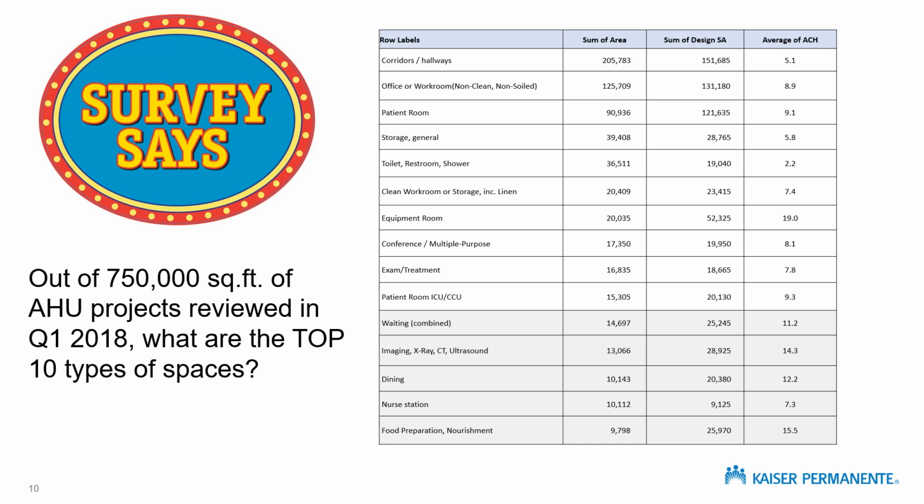Our average design engineer puts 5 air changes into those corridors. The code now in California and nationally is starting to line up around 2 air changes, and even that is completely unnecessary. In terms of cooling load or air quality, you really don't need to do anything more than fart air through the corridors. And so there's really a lot of energy that gets wrapped up in corridors.